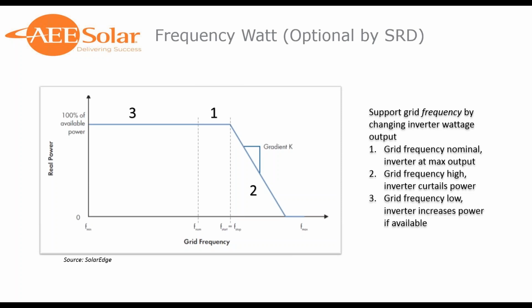This is, I think, really going to help in the scenario that we saw in the preceding slide. If the smart inverters see frequency and voltage rising, perhaps because inverters slammed back onto full power, and it sees that frequency start to rise, grid support inverters can actively curtail power to help maintain grid frequency.